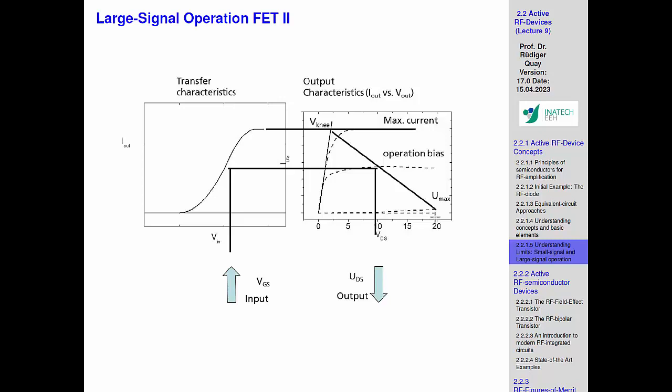So you get a very decent current change, but not necessarily a good voltage. That's the limit. And that's why in this curve, mobility versus band gap, we always want to go to the top right in order to increase the combination of the two. That is the key challenge.